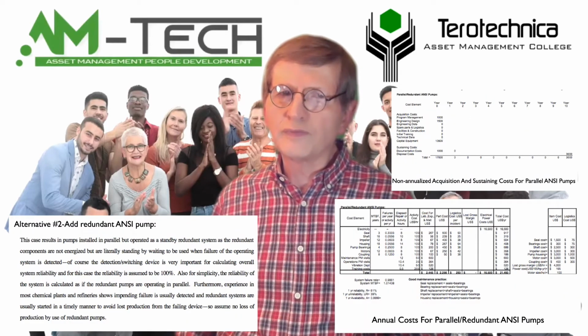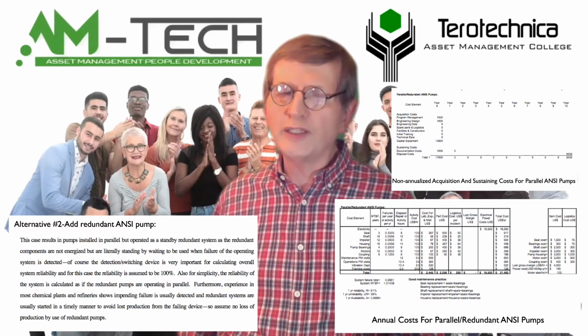Alternative 2. This case results in pumps installed in parallel but operated as a standby redundant system, as the redundant components are not energized but are literally standing by waiting to be used when failure of the operating system is detected. Of course, the detection or switching device is very important for calculating overall system reliability, and for this case, the reliability of this switching process is assumed to be 100%.